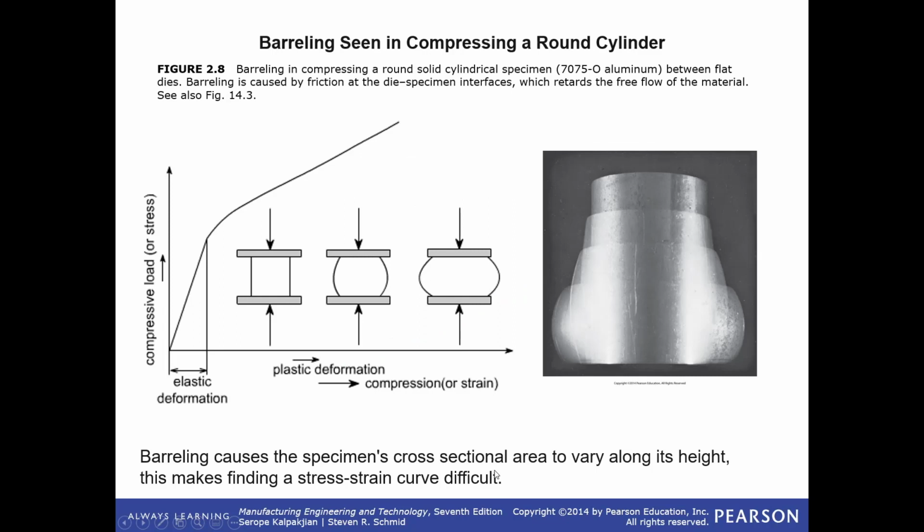All right. One other testing method used, not as readily as tensile testing, but it is used in various fields, especially if there's going to be any compression for parts. They're going to want to see when things start changing under compression. You can get a similar curve from compressive loading. So instead of tensile loading, you compress it, right? The difference here, and why this isn't used as much, is because of this barreling effect. What they show here is a barreling.